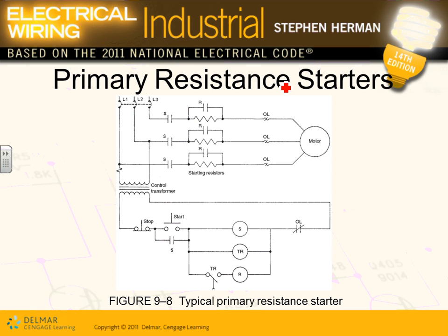So the smarter guys use something called primary resistor. The primary resistors do a very simple thing. If the voltage is 480 volts here, when you energize, you close these contacts. So now I will cut the voltage up to here, to the motor, say 240, momentarily. Because the leftover will be right across the resistor: 240 volts across the resistor and 240 here for a total of 480. So they cut the voltage, say, by half.